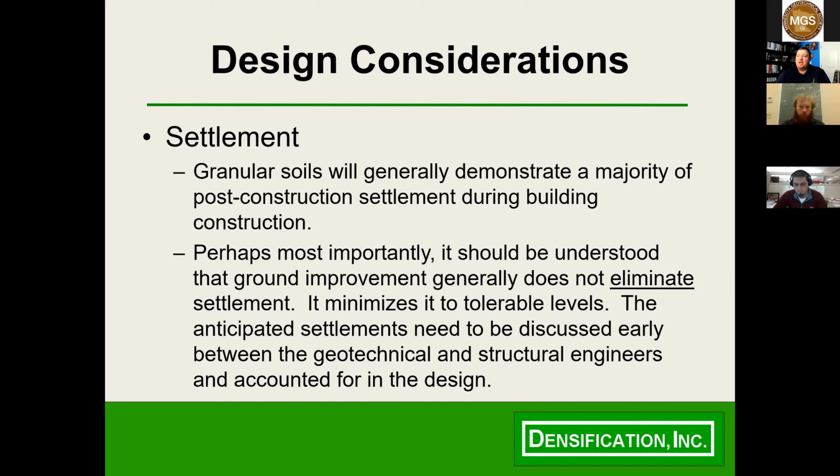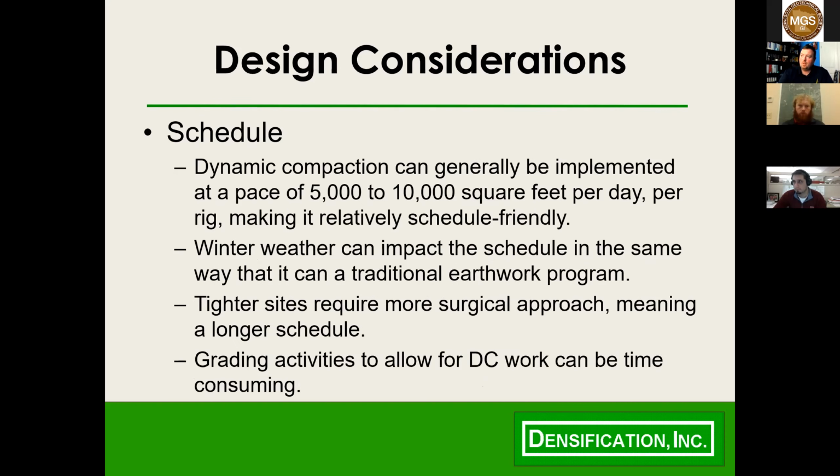And so if you've got a site that is one of these warehouses that's got super flat floor requirements and electronic racking systems and all this other stuff, where they can't really tolerate differential settlement, that plays into, can you use ground improvement, or am I looking at a structural floor slab? So it really is important to be having those conversations with the structural folks to make sure that everyone's on the same page going into a program like this.